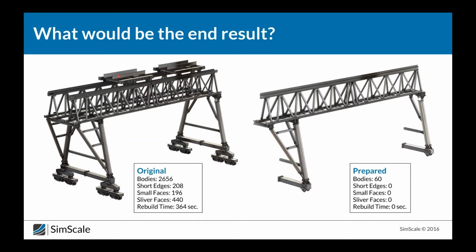So we can simplify by just removing that geometry and replacing it with a load in the down direction. Likewise with the supports at the bottom, these wheel assemblies are connected through a pin. Because they're connected through a pin, we know that the reaction forces must also be vertical, so we can remove those to simplify the geometry.